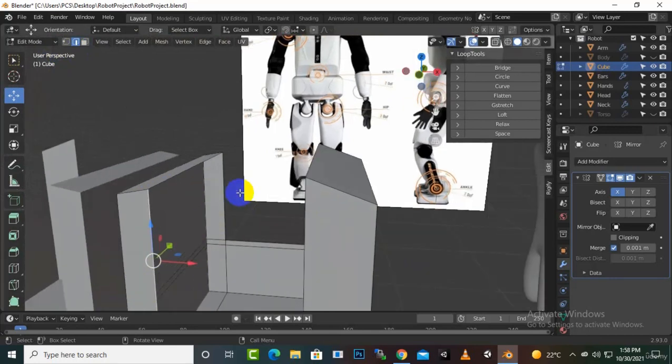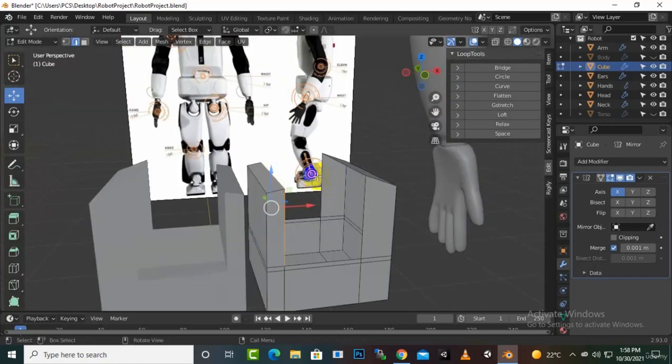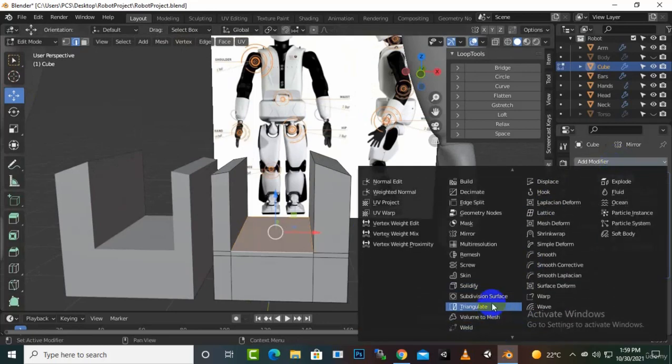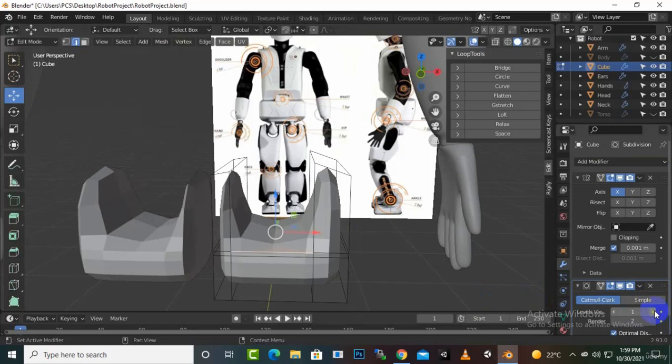So we'll select this loop and this loop, and shift alt click, with shift we can select both, and we'll just press F to fill out the faces, then this one and this one, and we will press F, then these two, this one and this upper one, and then we can press F.